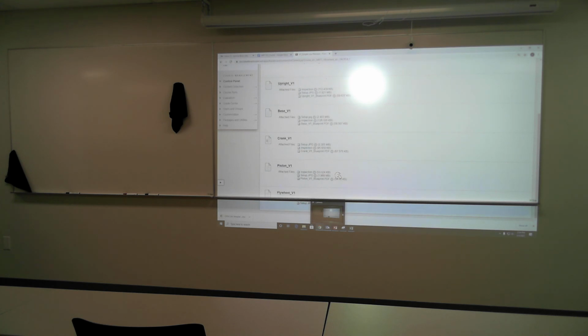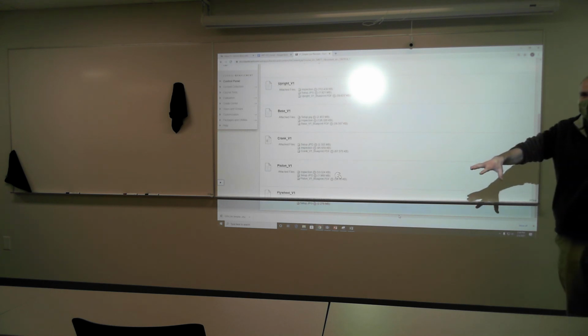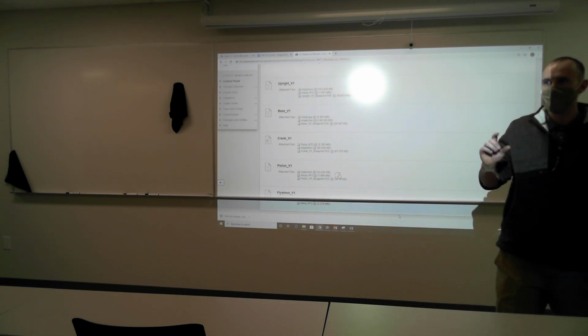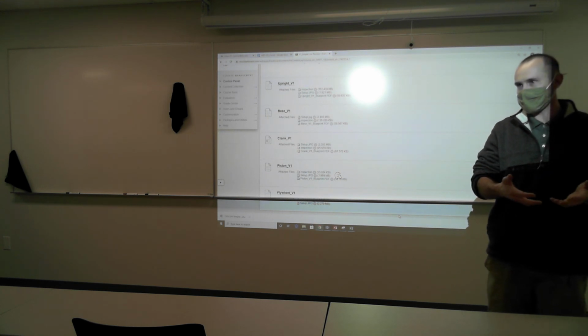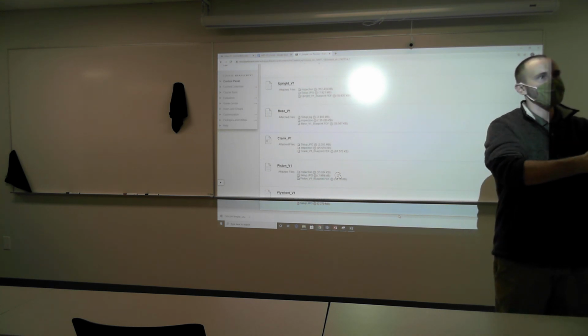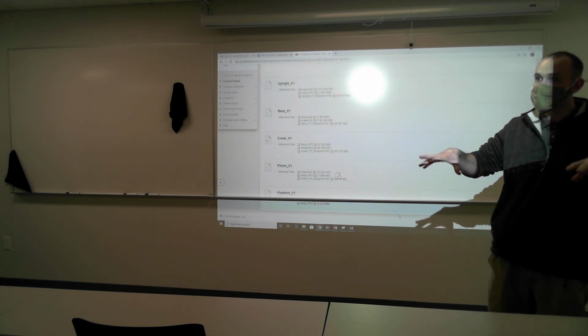What does FAI stand for? FAI stands for First Article Inspection. So the idea here is you're doing a first article inspection, meaning when I set up the machine and I'm going to cut 1,000 parts, I don't just cut 1,000 parts. That would be reckless. I cut one part, and then I inspect it myself to the best of my abilities, given the gauges that I have, and then I submit that to the inspection department. And that's where this class comes into play.